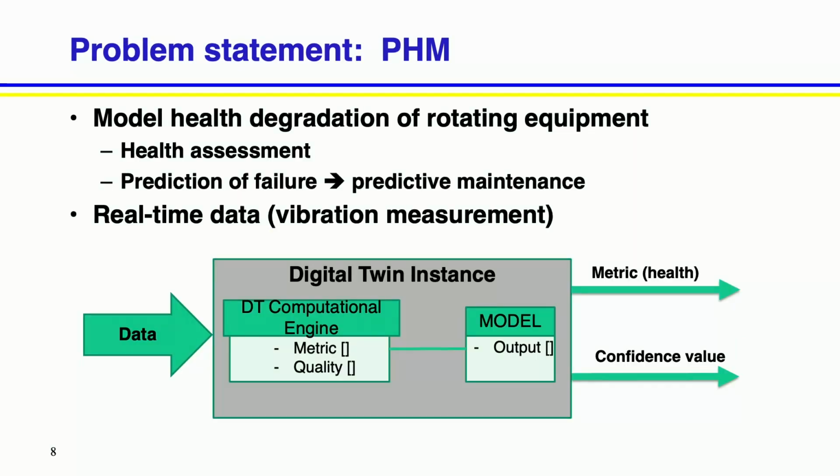So I'm going to talk, again, with what we think of as a digital twin. We want to have the data that's coming from the real-time process that goes into this digital twin of the process. And you can see there's no picture of a pump and there's no angle of rotation. But we're going to take some data out of the pump, and typically we're going to use a vibration measurement. And what we'd like to be able to predict about that is the state of health.